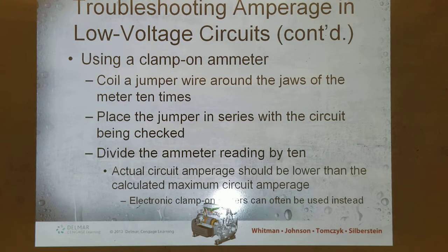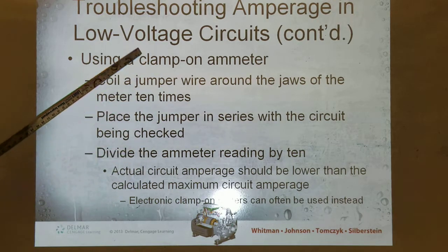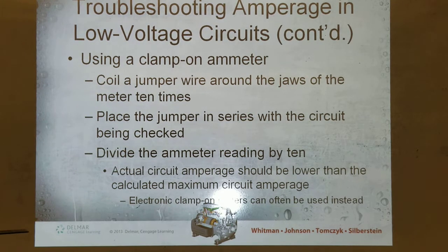I think we just talked about transformers that read the voltage. For one, you're gonna check and see if it's drawing too many amps. You're gonna check the amp draw and make sure you're under the maximum, and you're gonna have to figure out, like we just did, get the VA and divide it by the voltage. Another reason you're gonna have to do that is because you're gonna need to set that heat anticipator. But you guys won't have to worry about it as long as you stick with a digital amp meter.